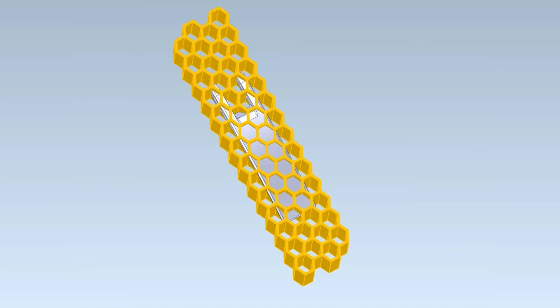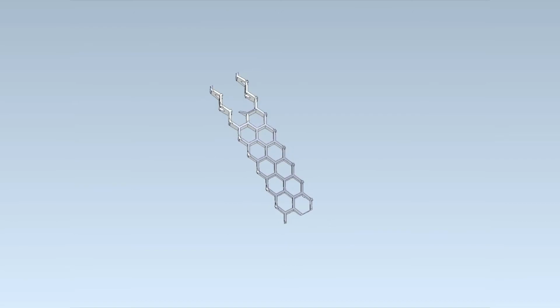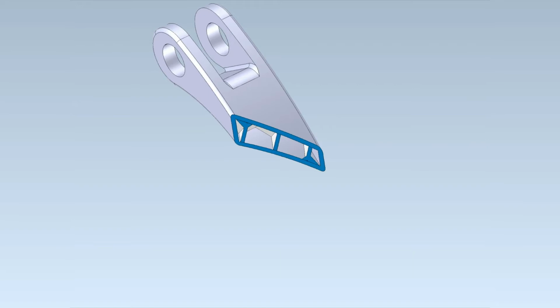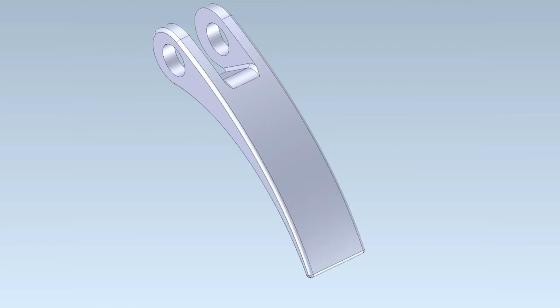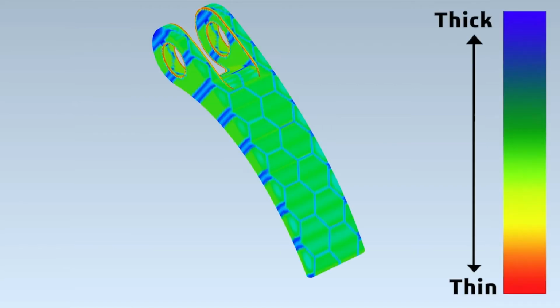With the aid of CGM Modeler's various modeling operators, a honeycomb structure is quickly created and trimmed with external surfaces of the original lever. Then the original lever is shelled to a desired thickness and subsequently united with the trimmed honeycomb structure. Now we have a lightweight yet stiff lever, which is custom designed for a professional racing team.